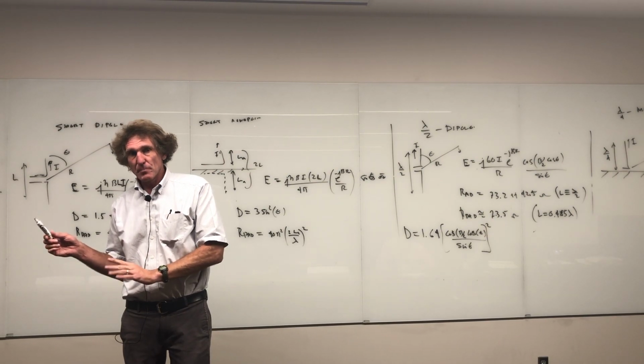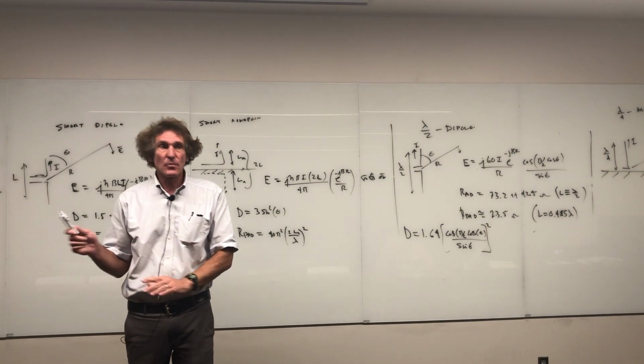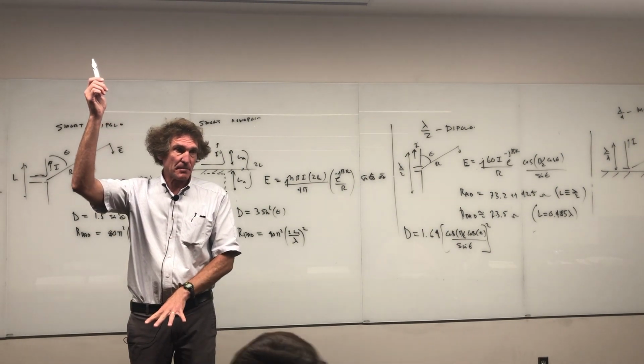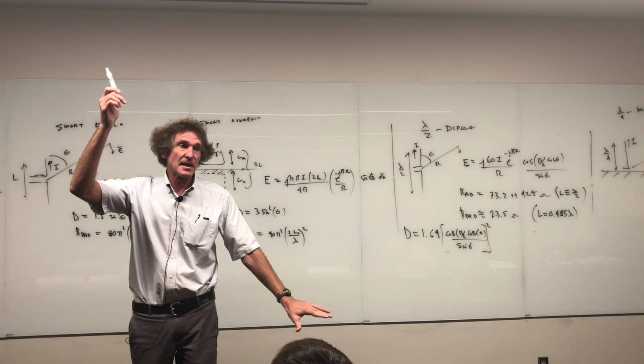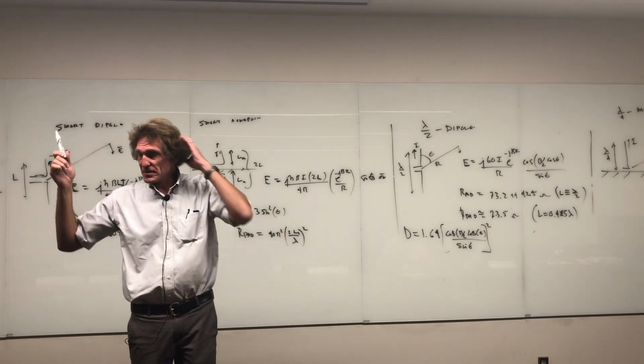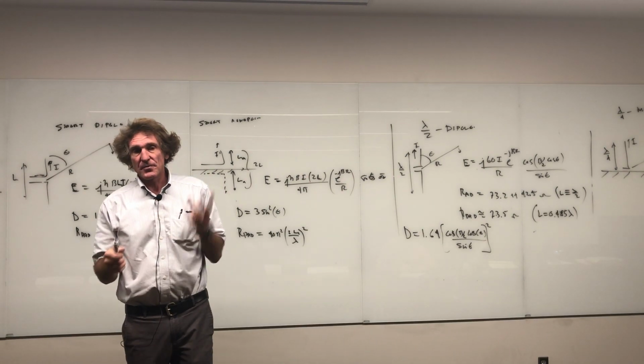One thing you're going to learn, practically speaking, if you are going to deal with an antenna where you're going to have an image and you're going to be broadcasting a lot of power, you don't want many losses in the ground. You'd like the ground to look just like a perfect conductor. Well, that's not feasible, but there's about 3 things they do.